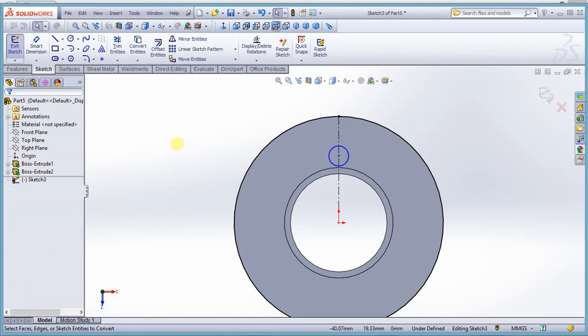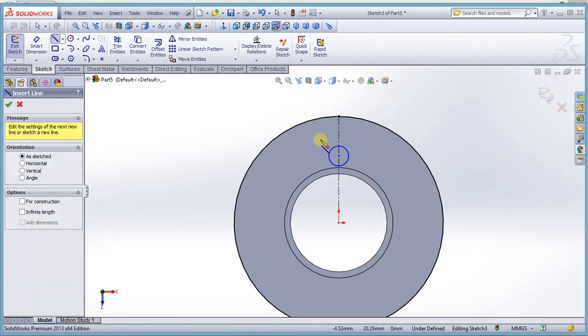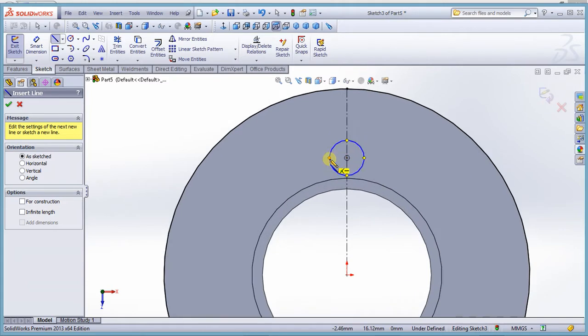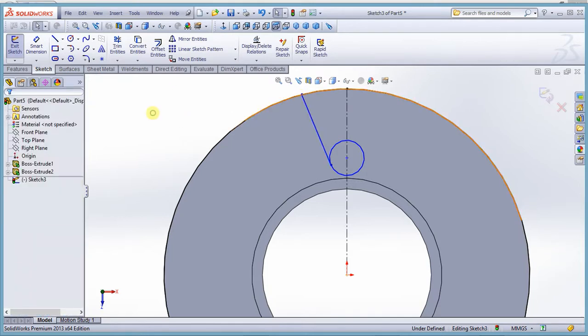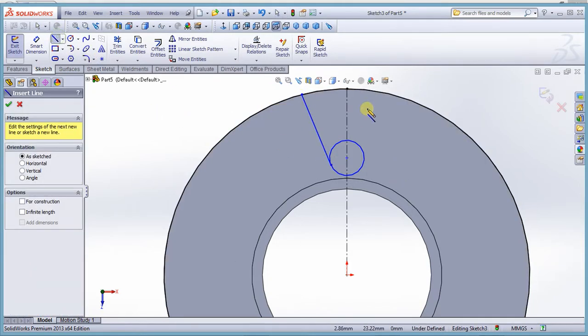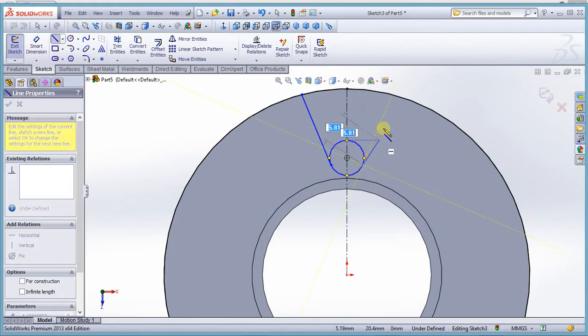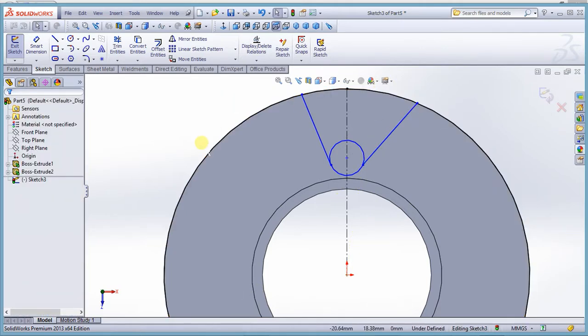Get that right? Okay. Now select a line from this point, not at the midpoint, at any point away from the midpoint. Select a line tangent. That's where to get the tangent line to this point. Select another line, at a point above or down, to get a tangent line to this surface and say okay.